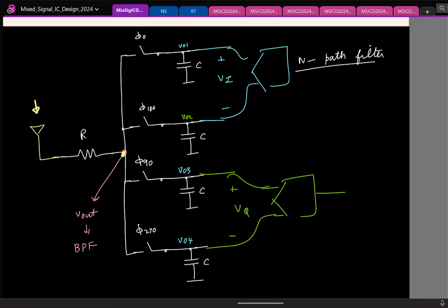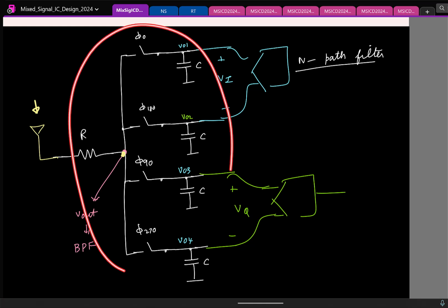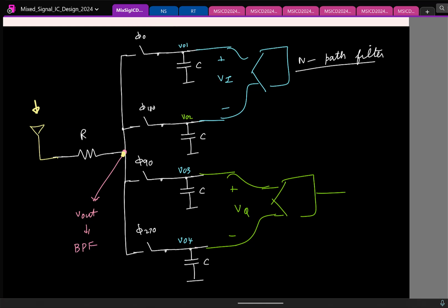Instead of the RC filter, if we place some kind of active filter initially when we started, and then we do that sampling modulation, you can do it, right? I'm not saying this is a simpler thing. That's what people have been trying to make better and better. The beauty of this is there is no active element required. If you want to use op-amps, the op-amps need to run at high frequencies, so designing will be a challenge. But of course, people are doing it.